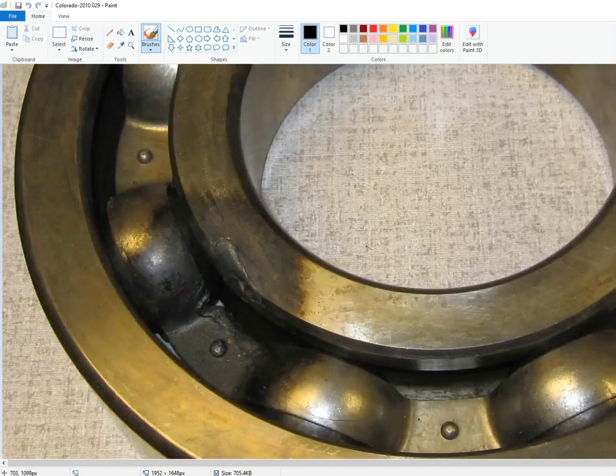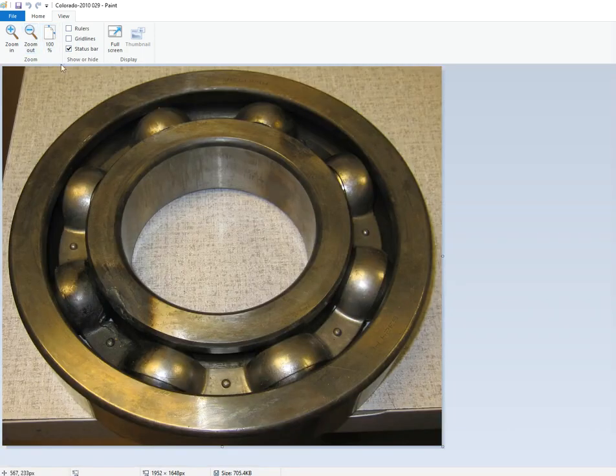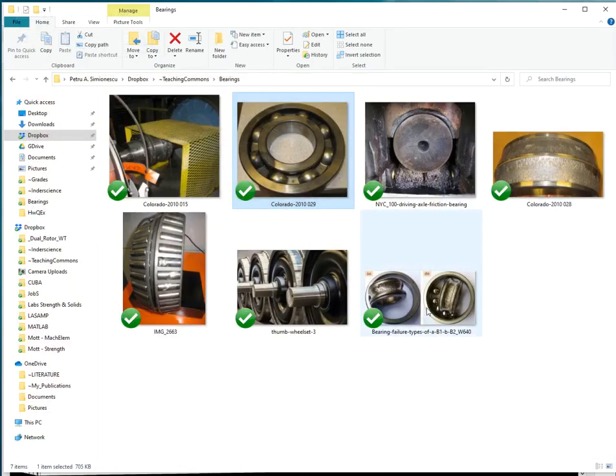because you can have, here, I believe there was a, so you're looking here at, let me make this smaller, what appears to be an electric discharge, which damaged the bearing. I know for a fact this was used with a wind turbine, so maybe lightning caused this damage. But in electric machines like generators and electric motors, you can have stray currents, and if the current is closing through the rolling element between the two races, you have sparks created, and the sparks damage the surface and could cause rapid wear of the bearing.